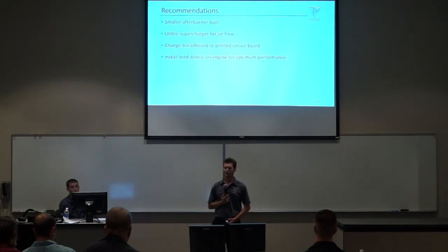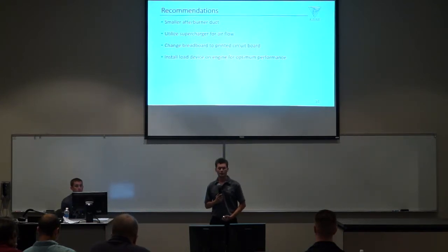And that's based on the idea that the turbocharger feeds around 2 cylinders at a time. So we have concluded that this is one of our biggest flaws, that the turbocharger is not a big enough turbocharger to sufficiently fill the area we've created for it. Also, another design iteration that we would try is to utilize a supercharger for the airflow.